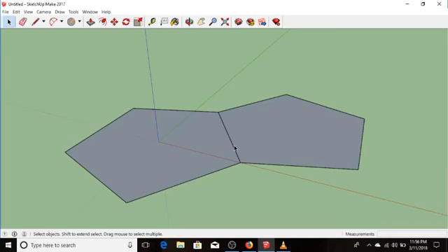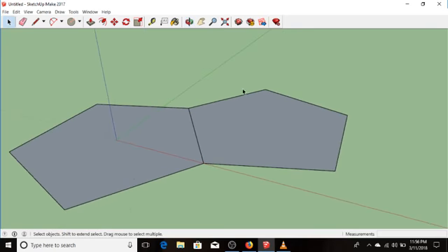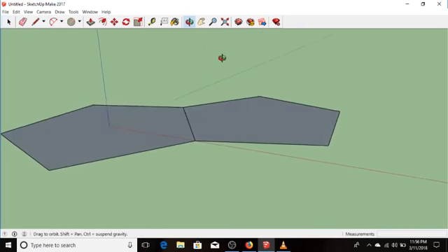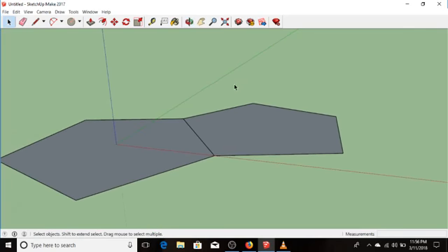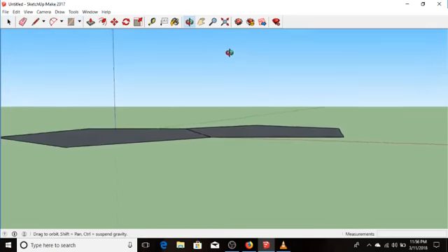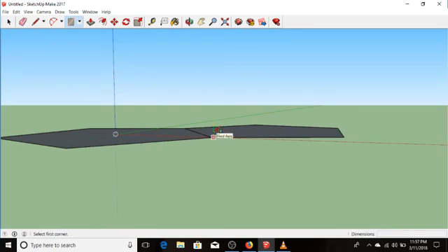Now I need to rotate this upward at the angle of a golden rectangle. I'm not sure exactly what a golden rectangle is mathematically, but golden rectangles are built into SketchUp. So R for rectangle. I'm going to start it there, draw it in this direction, and just move this around until it's in golden rectangle proportions. There's one. Golden section.